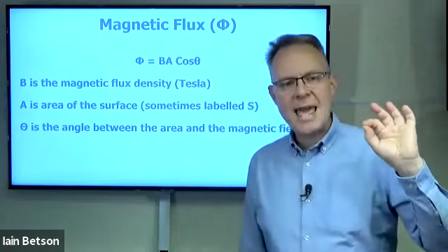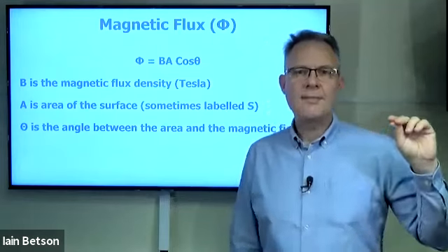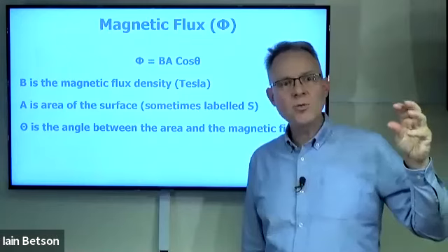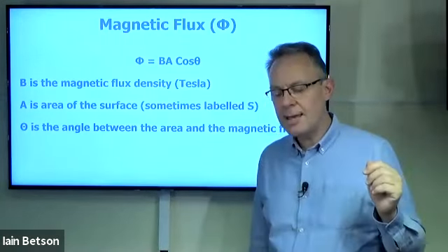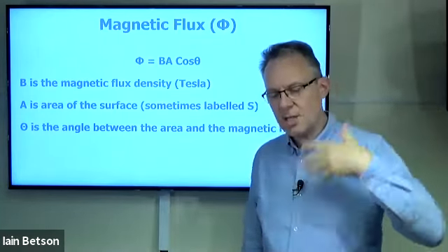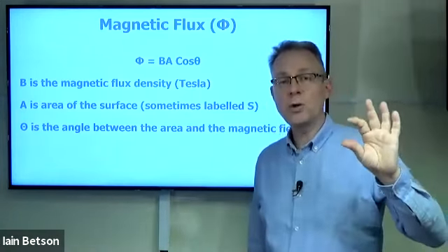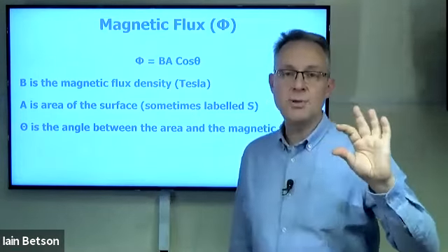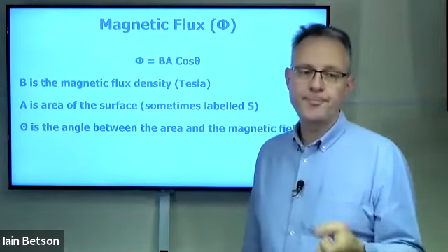So this is where we can see the area starts to make a difference, because if you don't have that area to record on, the signal's not going to be as high, it's not going to be as loud, and the remanence will be less, or the retentivity will be less, of course, and the remanence, therefore, when it comes to replay. And therefore, you always have tape noise, which is a constant, which is the oxide as it rubs across the head, and that is going to effectively appear louder, a thing called our signal to noise ratio, the difference between the wanted signal and our tape noise. And again, this will also come on to when we cover an issue called print through.